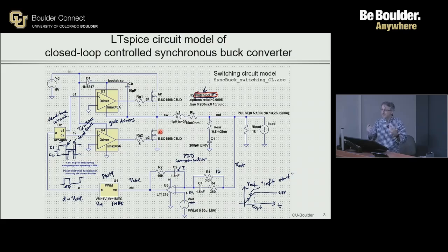Okay. So dead time is basically, from the safety point of view, you don't want to short this circuit path right here. And from the losses point of view, you want to have it as short as possible. In fact, if we had a different class, we would talk about ways to optimize the dead times. There are actually smart circuits that can do that in a variety of ways. But right now, we're going to stick to a fixed choice of some reasonable dead time. All right, that was a good question. Anything else on this SPICE circuit?